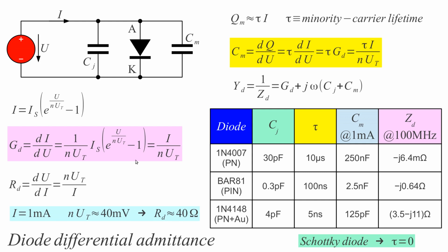But we have yet another effect. With diodes under the forward bias, when the diode equation holds, we have lots of electrons going from the cathode to the anode, and inside the anode region, they are minority carriers in the p-doped region, and they have to recombine before they transform from convection currents of electrons into conductive currents of holes.